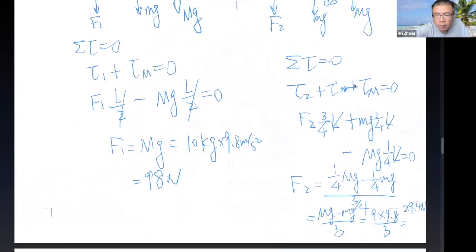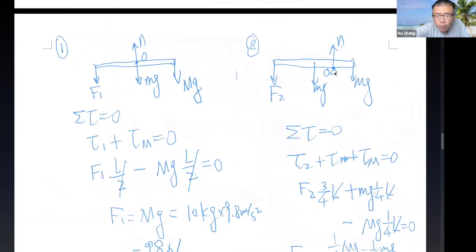The reason for that is we take advantage of this equilibrium condition. It's the torques that are balancing each other, not the forces. So if you put this length really large, you could actually have a really small force to lift something really heavy. Sometimes these lengths are called the lever's arm. Like this length or this length. And as you see here, the weight of the lever contributes as well a little bit. Not too much, but a little bit. So basically the idea is by moving the pivot point closer to the object, you could use a smaller force to lift something heavy.